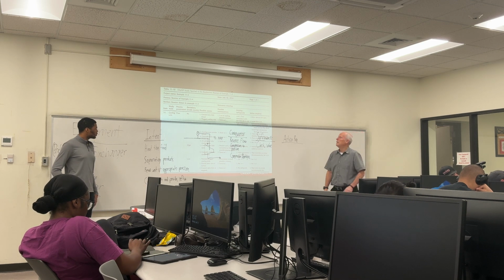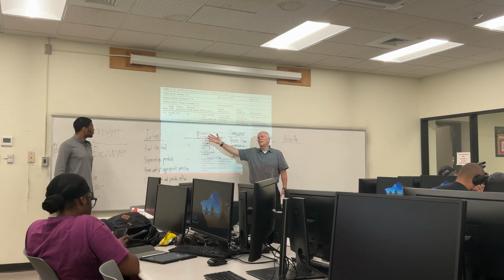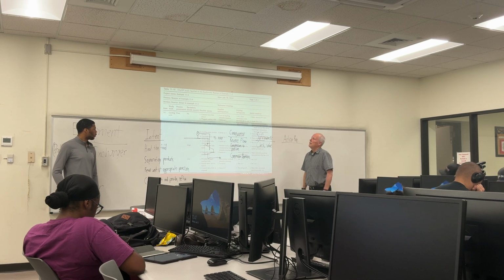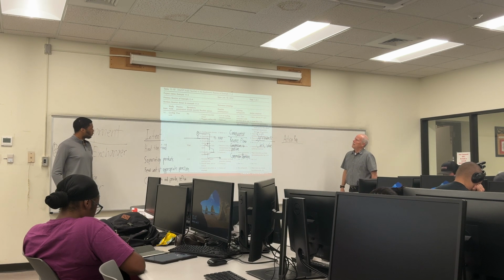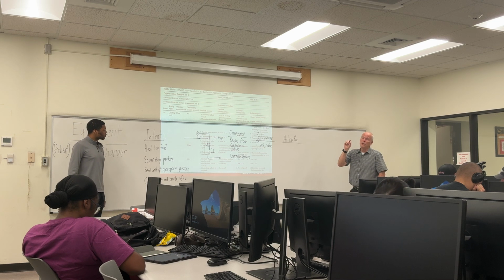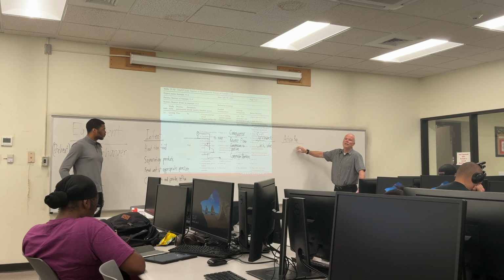So these things generally will send what's called a first out back to somewhere where you can look to see what happened first. That's kind of how you're going to know, because you're going to get a shutdown indication that comes up that says your compressor shut down. You're going to get that, and you could have an alarm on the control. So then what do you do about it? Compressor shutting down, boom, you got that alarm, what do you do?